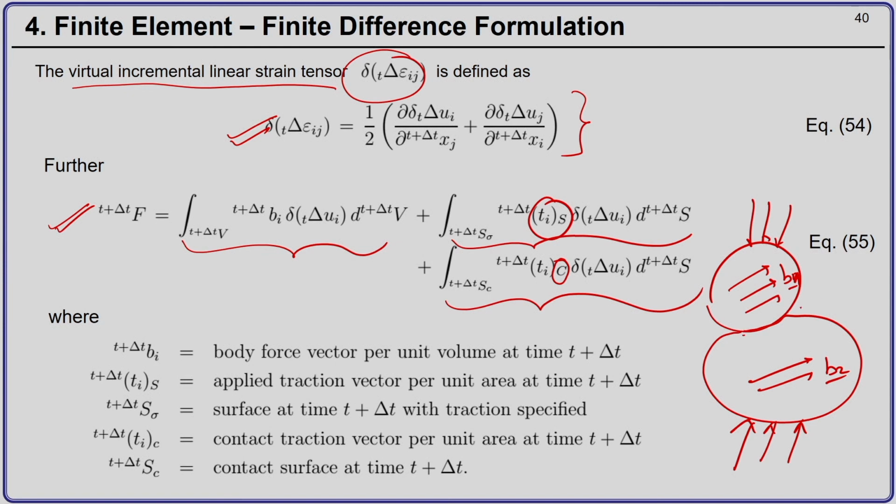And then when you separate these two bodies in contact, body A and body B, at this surface each body will experience what is called the contact traction. This body will have a compressive traction like this, and body B will have a compressive traction like this. In addition, if the bodies are sliding over each other and there is friction, there will be two kinds of tractions.